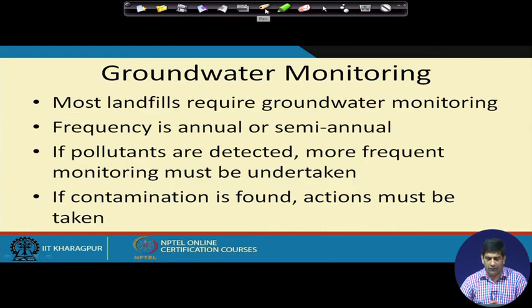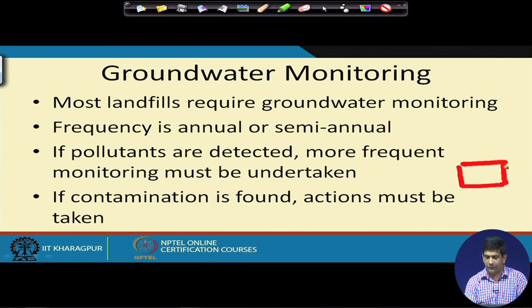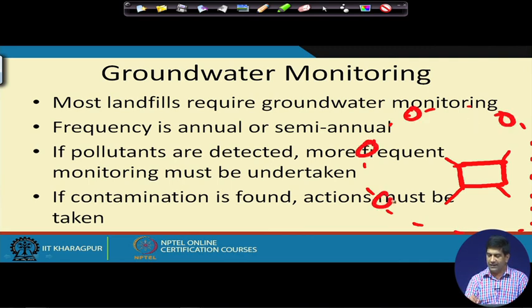Then groundwater monitoring. I mentioned, using that sketch, the periphery of the landfill. If you look at the plan view of a landfill, from the top, this is your landfill, and the whole landfill boundary will go out of this screen here, but all along this we put several wells. We monitor the groundwater from these wells. The reason for doing that is to find out if there is any contamination happening from the liner system, if the leachate is passing through the liner system and contaminating the groundwater.